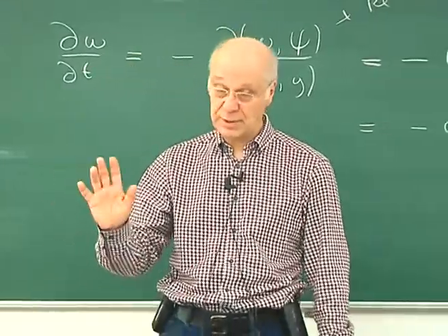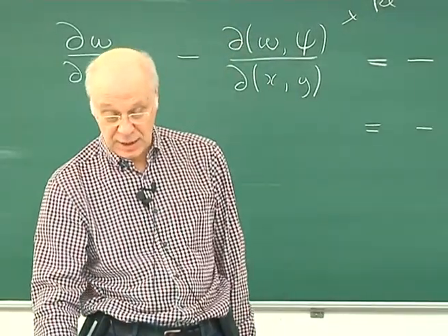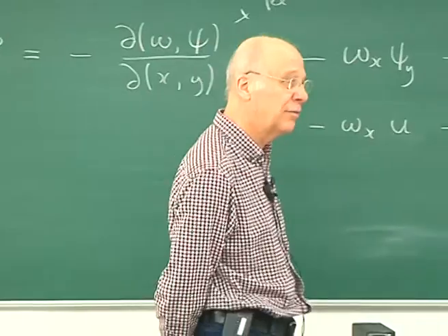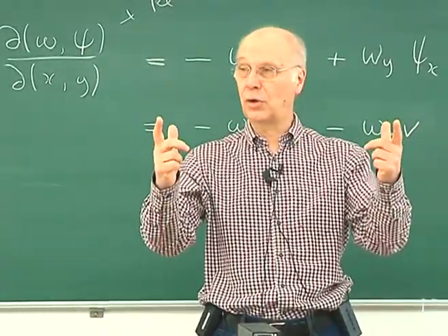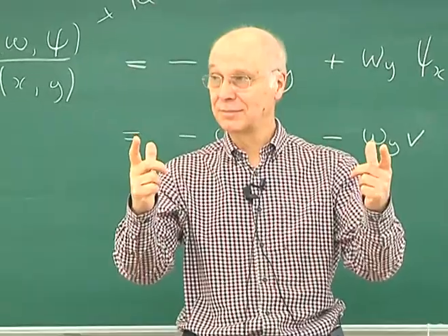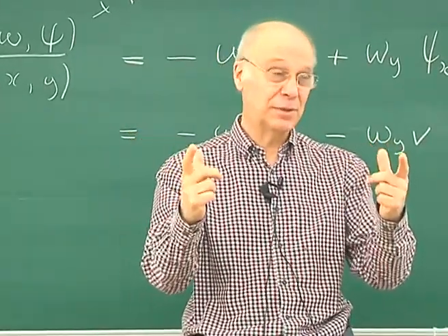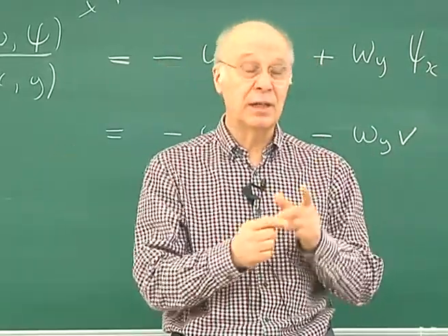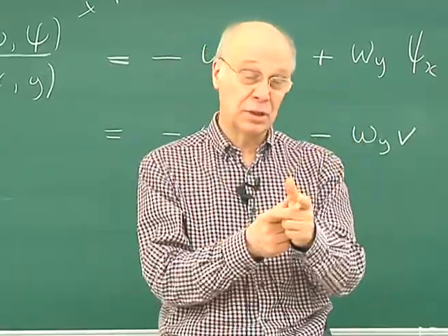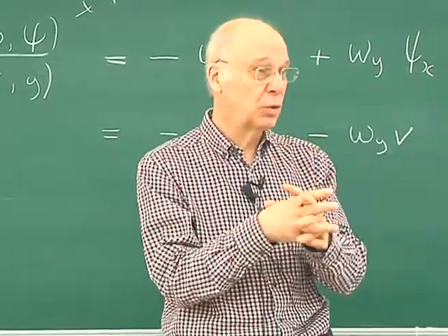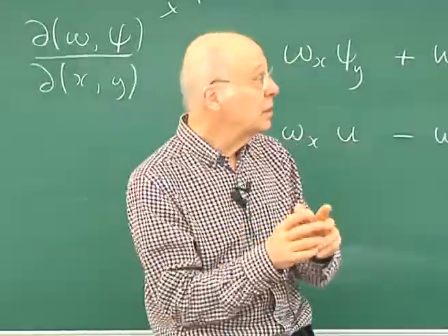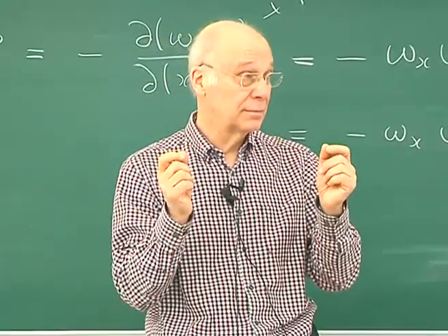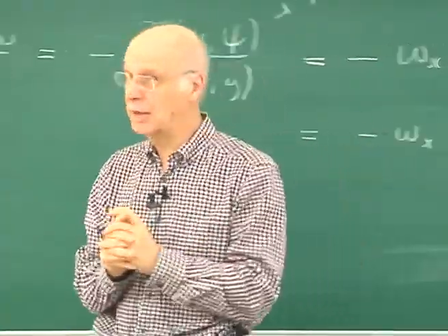Okay, so I've talked in 2 dimensions about triangles. For rectangles, it's pretty obvious what you can do with a constant. You can't have a linear function that fits 4 points in 2 dimensions, so you can't have a linear representation. But there are things called bilinear. It is linear in one variable and linear in the other variable. If you make a product of a linear and a linear, it is a quadratic, but it's not the general quadratic. There is no xi squared or eta squared there. There's only xi eta. So it's a restricted quadratic.